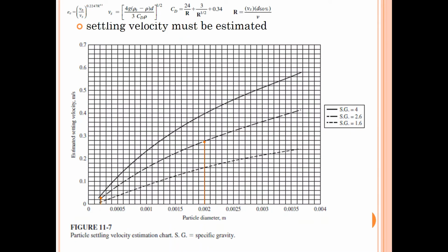Okay, but there is a problem. You see here, the porosity of the expanded bed is related to the backwash velocity, particle settling velocity, and Reynolds number to the power 1. So we have to find the particle settling velocity to find the expanded bed porosity.